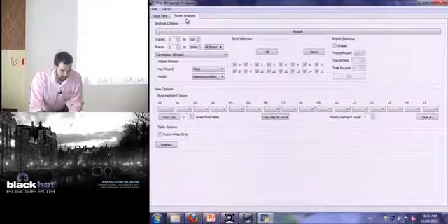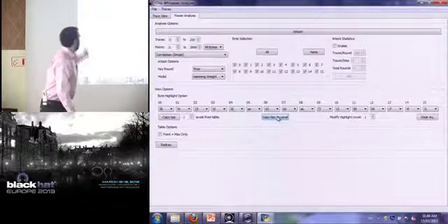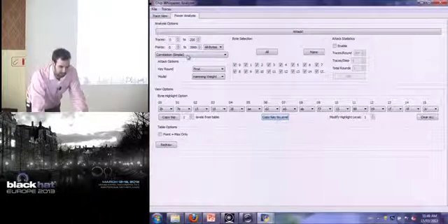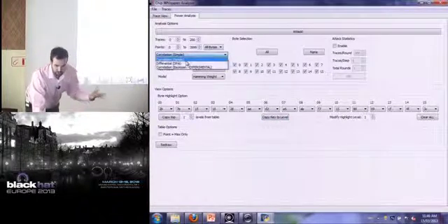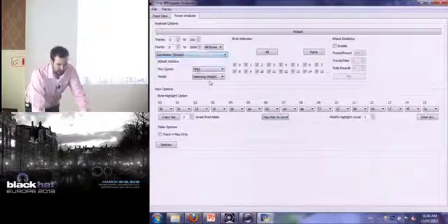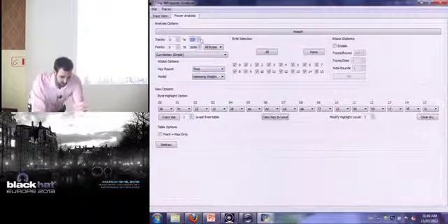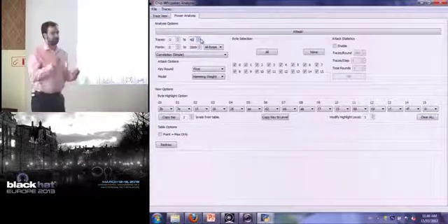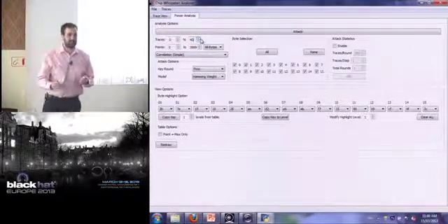For doing the actual power analysis, we can select, as I said, this type of attack, correlation, or the original DPA. We can select Hamming weight or Hamming distance type models and select how many traces. So remember when I said, in that example, the DPA, I was putting in 7 traces.